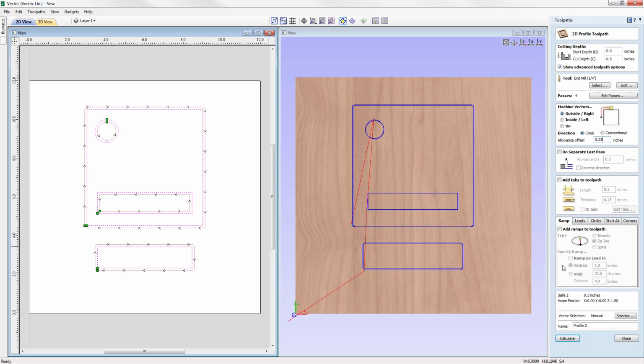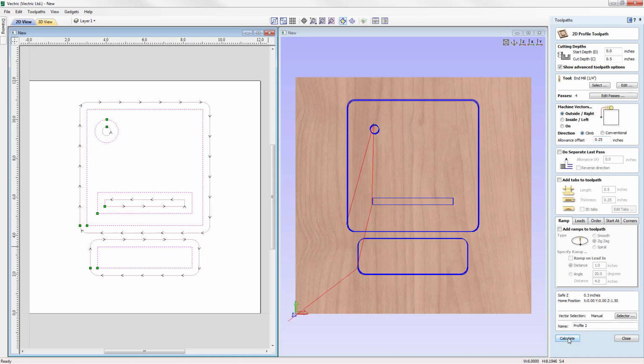And then what we could do is we could go ahead and just press Control and calculate. Okay, so that's just going to update that without going into the preview toolpaths form. And we can see that's been updated. Okay, so it's a little tricky to see the actual tool path here using this option. So we're going to go up the top, and we're just going to switch on to toggle the solid view this time. Okay, so this purple colour actually represents the cutout of the part. So anything that's purple will be removed away from our material. And we can see there that we have a distance here, and it's cutting away from our original vector by 1/4 of an inch. And the same applies on the inside also. So we're creating extra material, leaving more material on using a positive allowance.